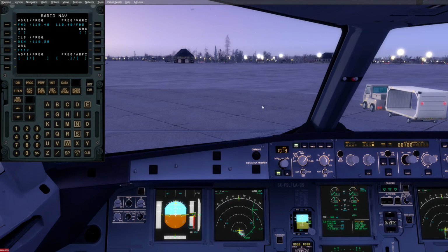And if they're centered, the bearing pointers are off. So now I have a bearing pointer that points to FMD. And you'll see bearing pointer 1 is VOR1, FMD, which is 3.8 nautical miles back behind me. So that's it for radio nav.